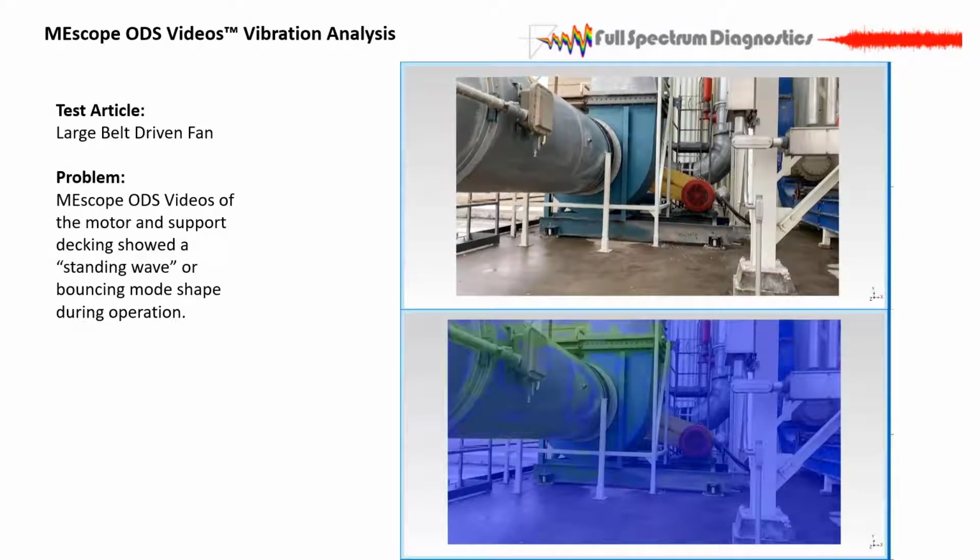This is the fan unit that we just talked about, and I like this view. This was also a little backwards. We did the ODS on the floor first. So we gridded out the floor, took a whole bunch of measurements, and from underneath we could see where the stiffener I-beams were, and there was really no way of stiffening this floor. There were a lot of folks that didn't want to do the isolators. They didn't believe in them, and they wanted to run a bunch of beams everywhere. But with the way it was set up, such large spans, it was really impractical. It was difficult to do it that way.